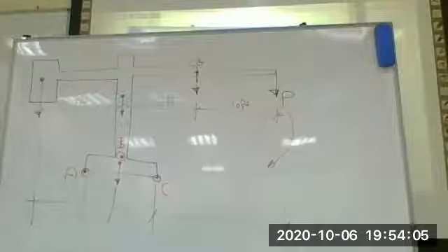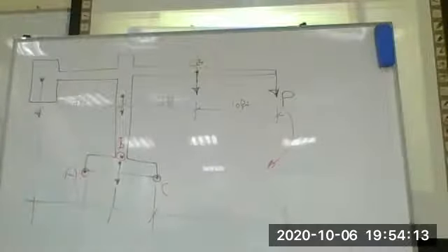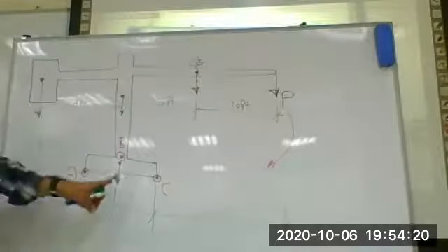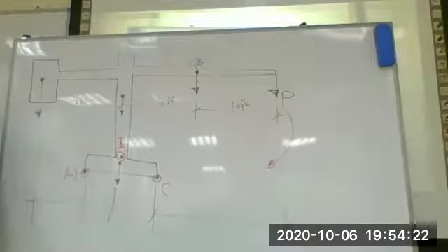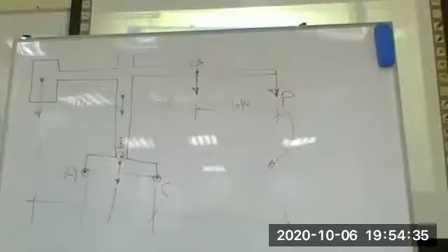Okay, sliding is different. Sliding is friction. It should be the sum of all the vertical forces, divided by all the horizontal forces, multiplied by the coefficient of friction between the foundation and the soil. We call it tan phi, or friction coefficient. The factor of safety should be more than 1.5. Later on we'll discuss this in soil. What is the equation?